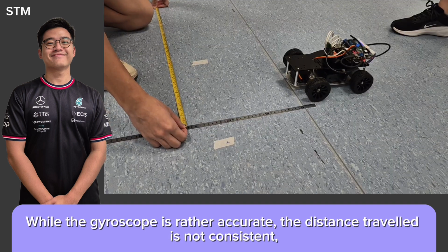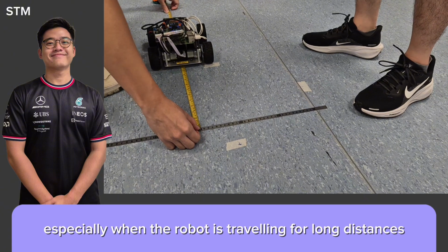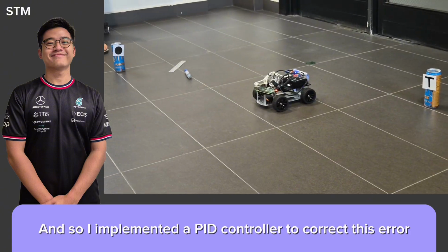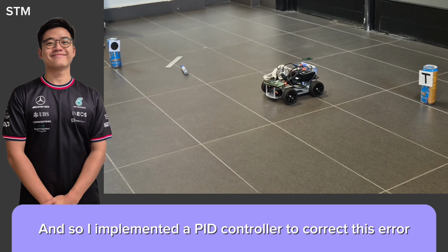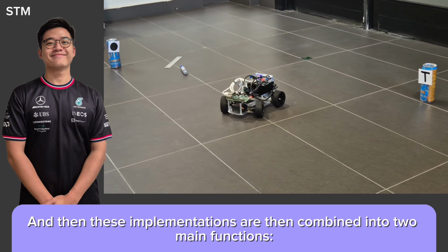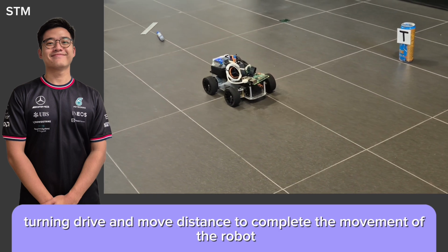While the gyroscope is rather accurate, the distance traveled is not consistent, especially when the robot is traveling long distances. And so I implemented a PID controller to correct this error. These implementations are then combined into two main functions, turning drive and move distance, to complete the movement of the robot.